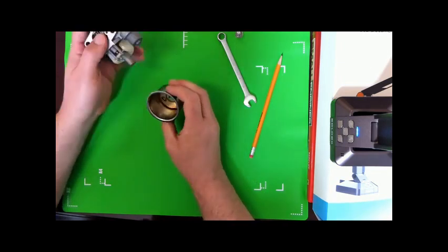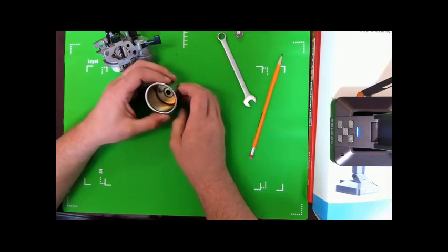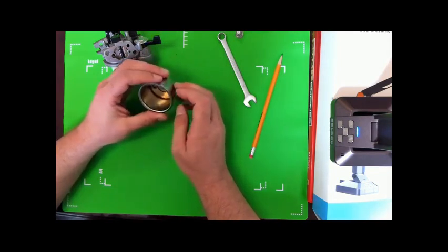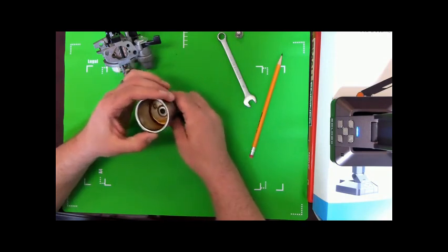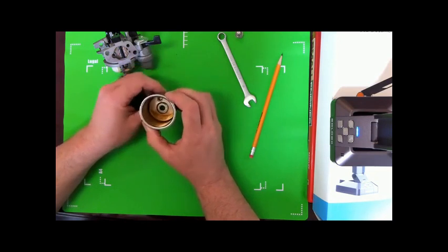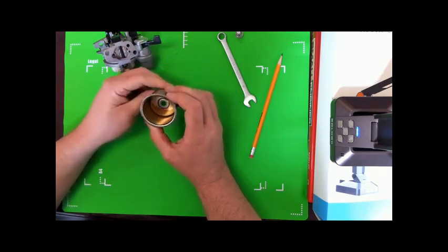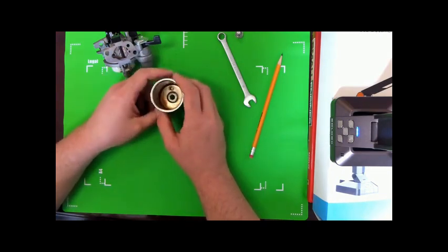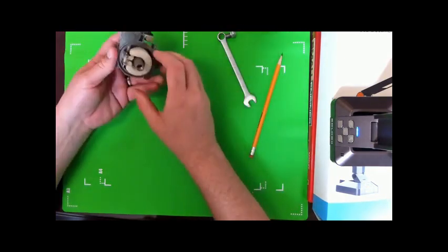As we open up the bowl, you'll see there's some residue in there. That's the remnants of gas, and most likely that's the remnants of ethanol, which we'll talk about ethanol fuel in a little more detail, and it's probably not necessarily a good idea to utilize ethanol fuel if you're going to store these engines for a long period of time. I usually end up with a gallon of ethanol gas just because it tends to be cheaper, and we don't run these engines enough to actually cause much damage.